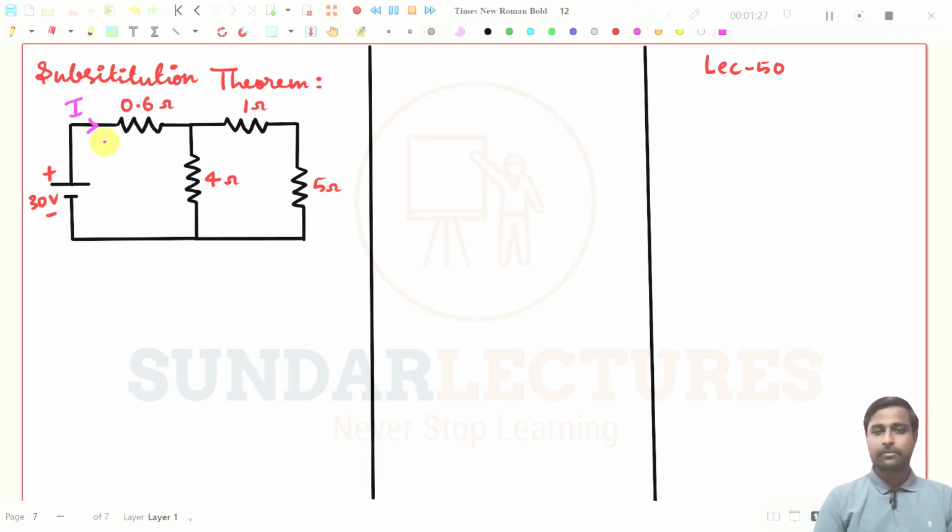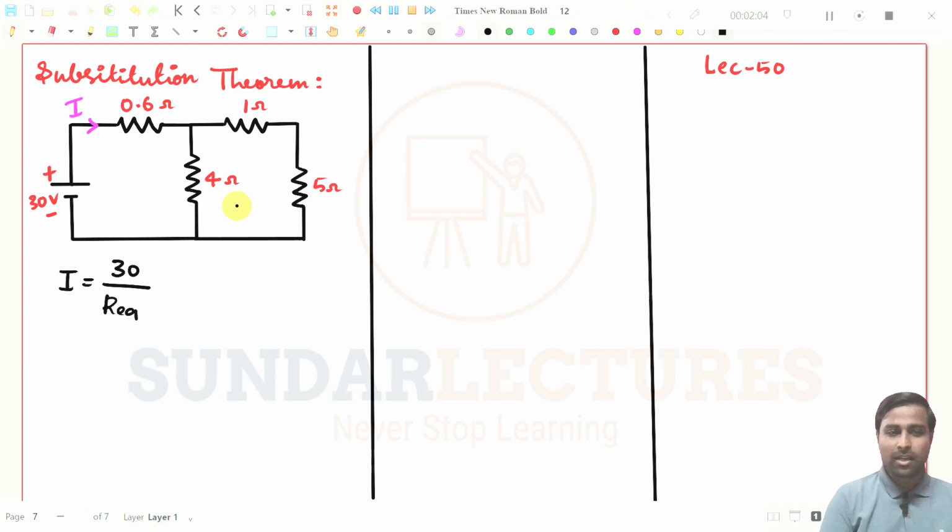You see these two resistors are connected in parallel, right? This 4 ohms resistor and this 6 ohms resistor are connected in parallel, and this whole network is connected in series with this 0.6 ohms resistor. If you want to find the total current I, I will simplify this whole network to a single resistor, and it will be the voltage 30 divided by R equivalent.